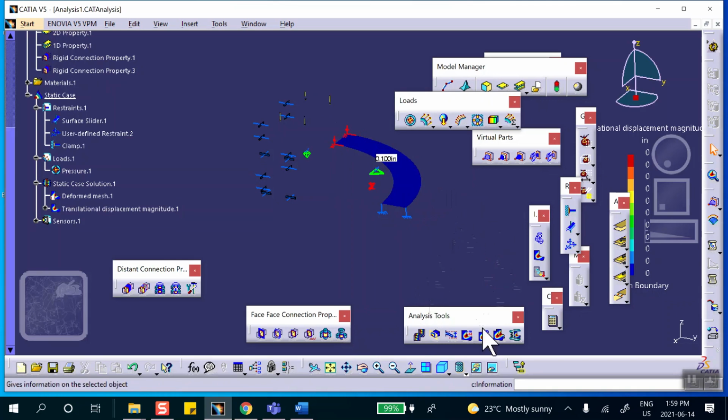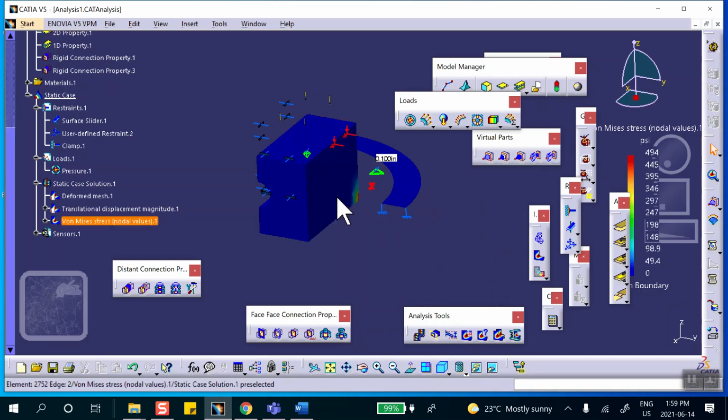And if you look at the stress distribution, the beam will have stress in it. Of course, you cannot plot the stresses in the beam. And yep, this shell does not go anywhere because the only thing that connects this to that solid object that moves is this beam, but that beam is coming to this point that is fixed in space. So this shell does not see any displacement at all. There's nothing wrong with it. This is the way it was.